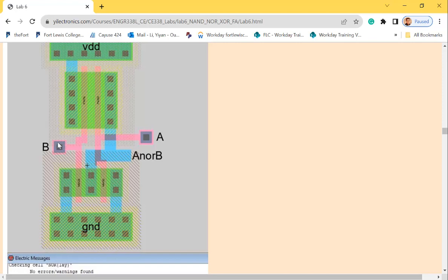And after that, I directly have a via, the polysilicon to metal one via, right next to it. This one I cannot because I got a metal 1 here, so I cannot make this too close to it. There's a minimum distance between metal 1s. Remember the design rules I just talked about?